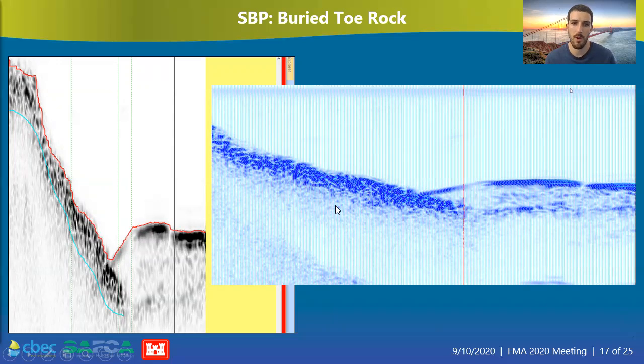So with this data, we're able to look at the riprap and note that it's contiguous all along the bank. There are no pockets of launching material that has reduced its thickness or slope breaks that may indicate some prior event that manipulated this sloped surface.